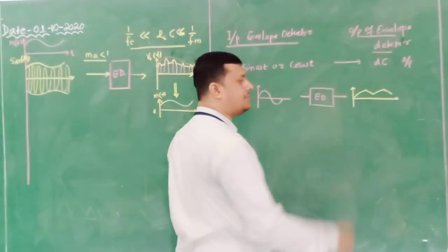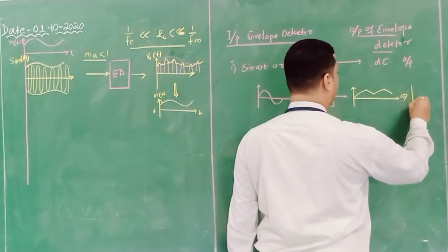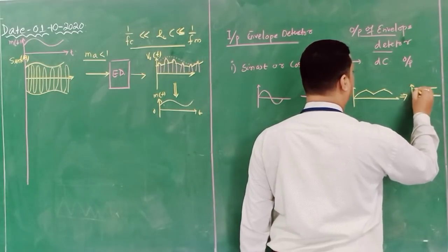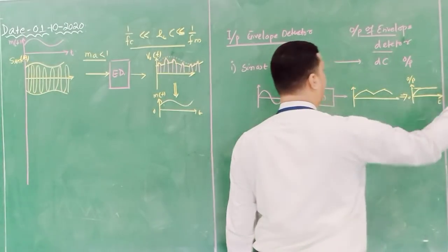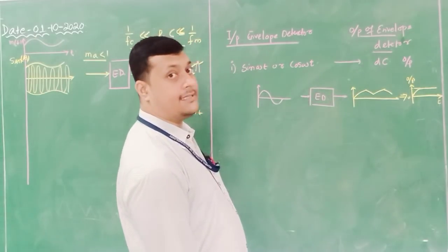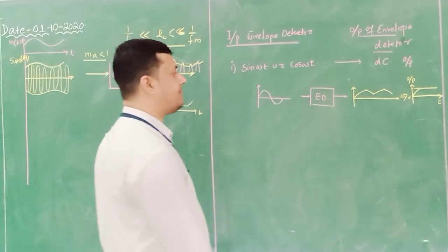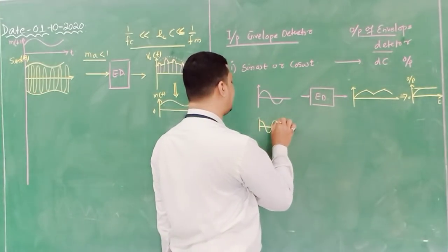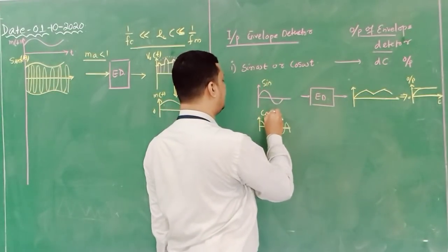First charge, then discharge, then charge, then discharge. Now if it is passing through a smoothing filter, it will look like this. That means after a certain amplitude, it will identify a constant output when the proper envelope detection condition is satisfied. So this is the output. Similarly, if I am providing a cosine signal, like this is the sinusoid signal, this is the cosine signal.